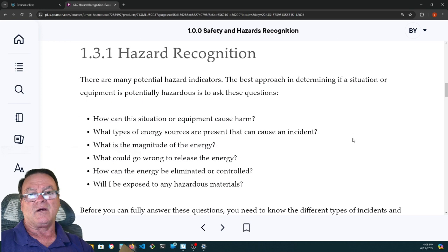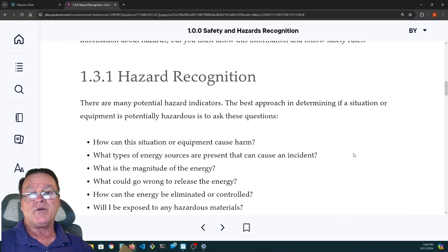If you're ever working in an area where they use ammonia for refrigeration, you need to know where the windsock is, know where to find it quickly. They'll have a flag called a windsock, and it shows the direction of the wind. And if there's a release of chemicals, you want to run perpendicular to that flag. You don't want to run into the wind. You don't want to run away from the wind. You want to run across it so that you can get out of the hazard.